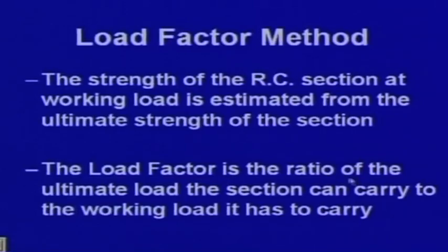Load factor is the ratio of the ultimate load the section can carry to the working load it has to carry. So, from this load factor we can find out how much maximum it can take. Whatever working load is given and whatever ultimate load it can take, from the ratio we can find out, and that is why we call it load factor.